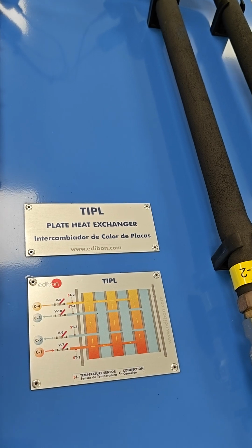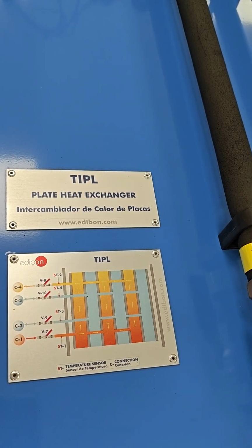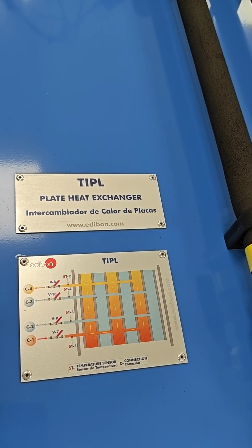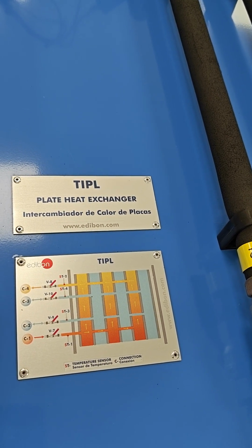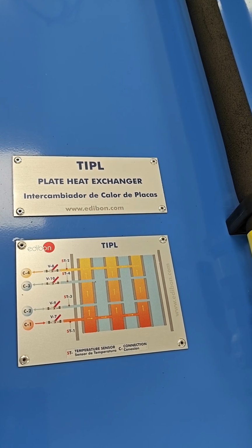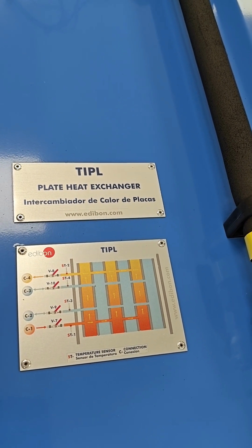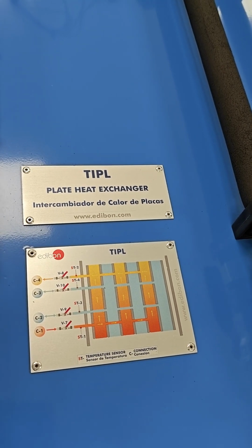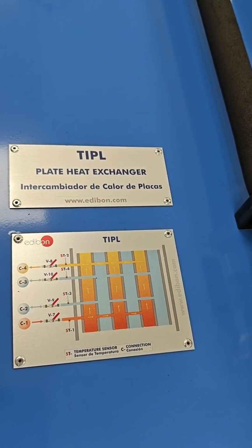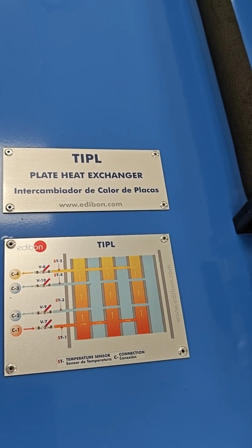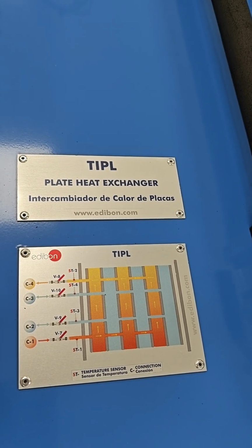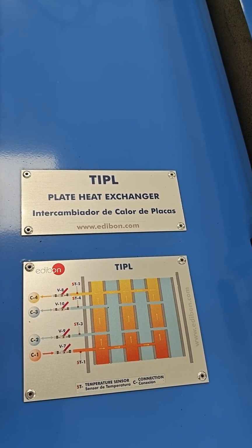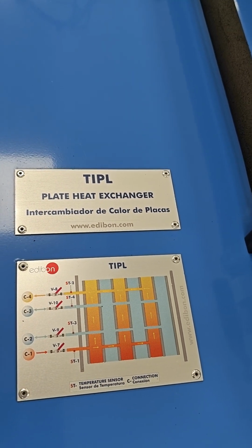On the plate heat exchanger unit, there is a schematic also shown here how the heat exchange is taking place. Red color indicating the hot fluid flow and blue color indicating the cold fluid flow. So inside the plate heat exchanger, a series of plates are assembled together. Like for example, in here 20 plates are assembled together to make up the complete system, and in alternate channels like 1, 3, 5, 7, 9 and so on, hot fluid flows, and in the other channel 2, 4, 6, 8, 10, and so on, cold fluid flows.